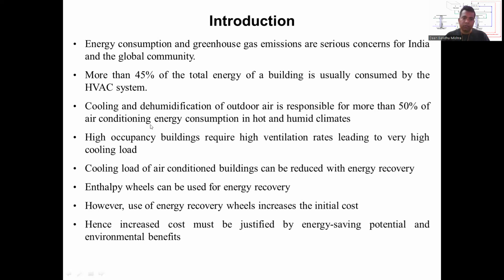So generally, in a conventional air conditioning system, when the outdoor air passes through the cooling coil, it is required to be cooled below dew point temperature in order to cool and dehumidify. And if the outdoor air is very humid, meaning the latent load is very high, it may be required to overcool, and further, before supply to the conditioned space, it is required to be reheated. This further increases the cooling load of the air conditioning system.